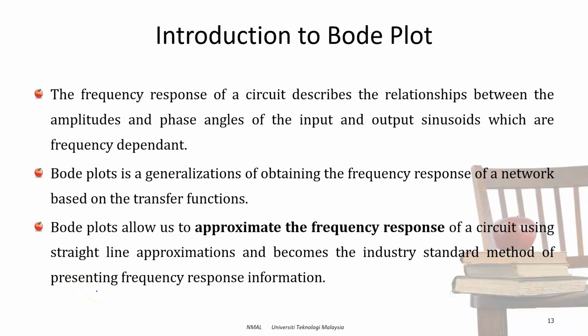This is because if we want to plot the frequency response over a very large frequency range, we need a very large graph. When we use a Bode plot, it is generalized based on that frequency response, so we can plot a larger frequency range in one graph.